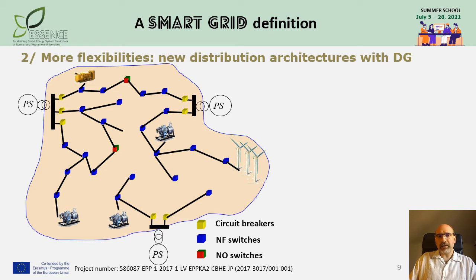So let's think about what the colleagues in Denmark did face when they had their energy transition in the 1980s. At first, what they created as a simple solution was, okay, let's close some loops in the grid wherever it is necessary, so as to increase the hosting capacity. And of course we can think about looping, but why not meshing, and meshing even more?